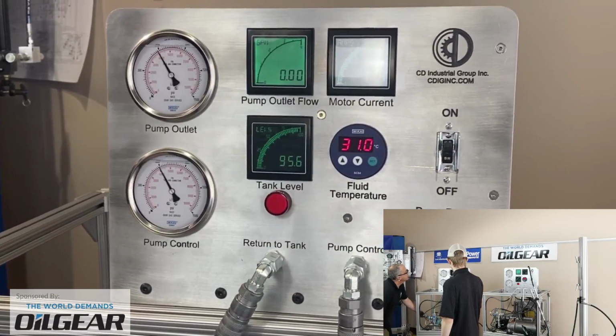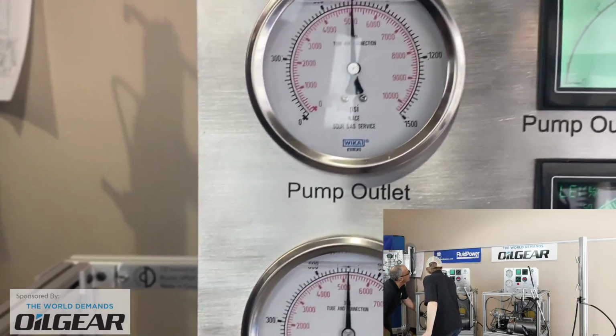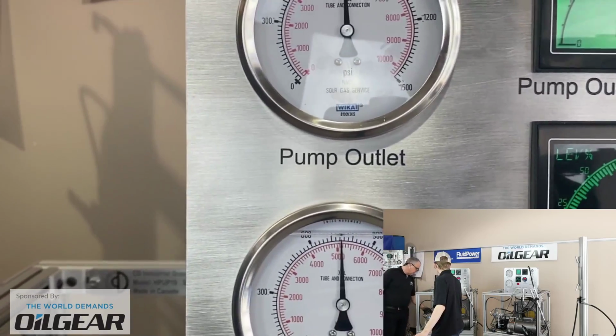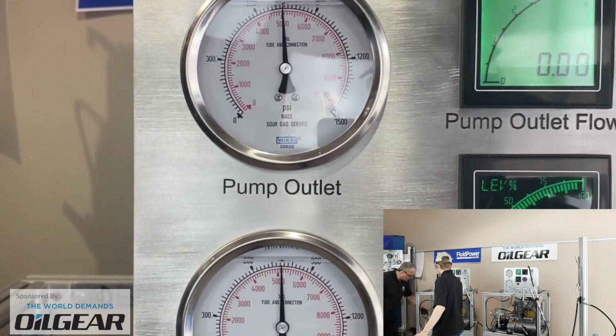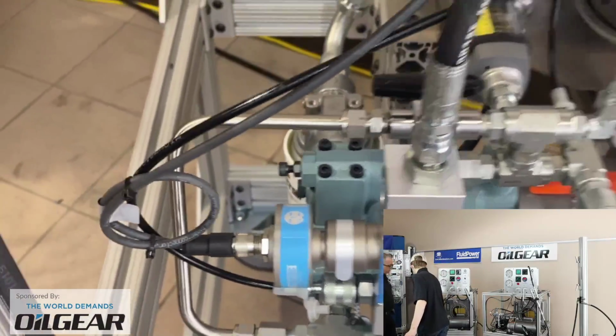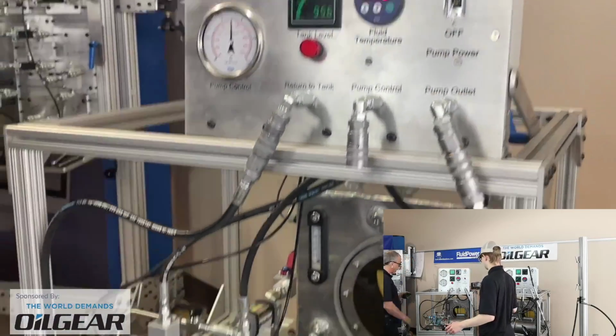So there we are back at 600. What did I say? Oh yeah, we wanted to go to 750. Perhaps that's our correct setting. And there it is. And of course, then we would apply the correct torque to the jam nut and lock it so that it doesn't move after we're correctly set. In this case, we can also adjust the maximum volume.